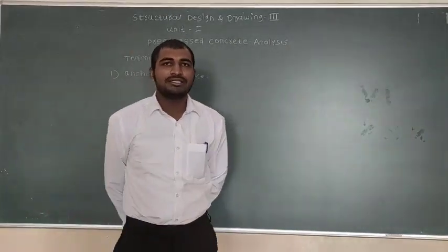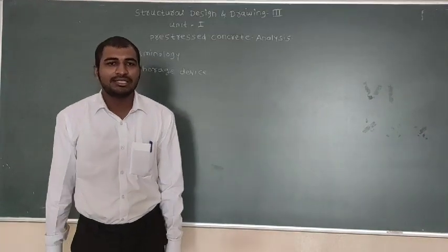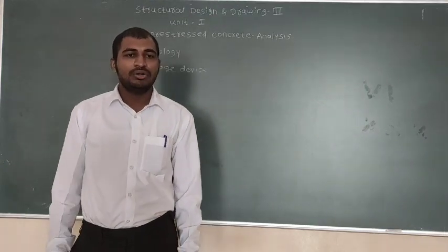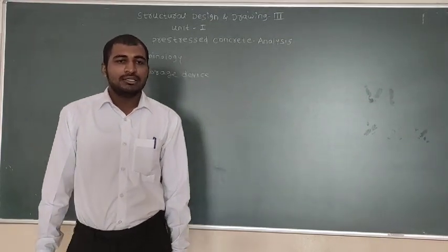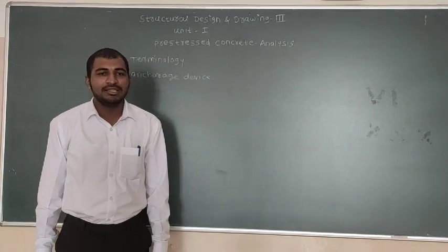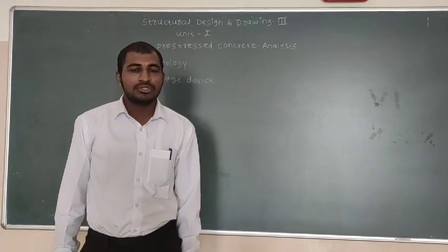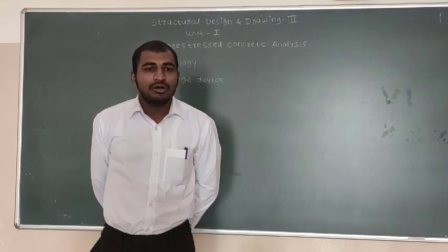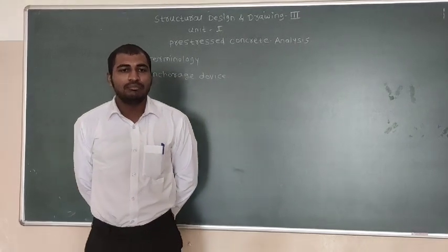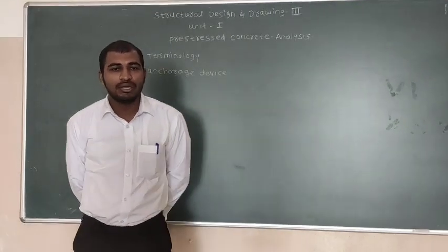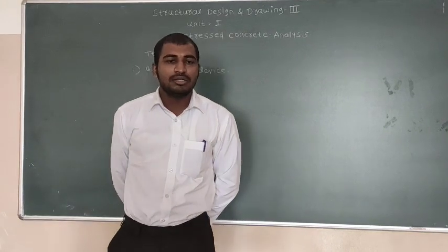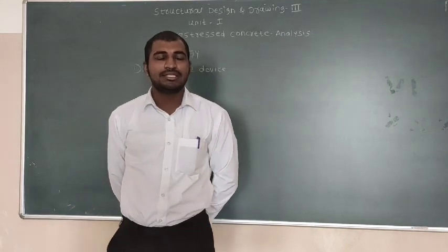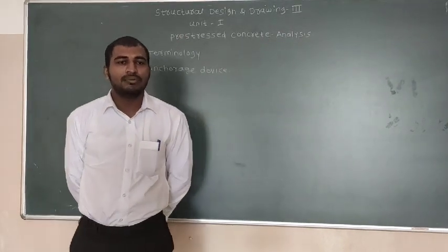First is the anchorage device. What is the anchorage device? This is a device generally used to enable the tendon to impart and maintain prestress in the concrete. The commonly used anchorages are the Freyssinet, Magnel-Blaton, Gifford-Udall, Leonhardt, Roebling and BBRV systems.